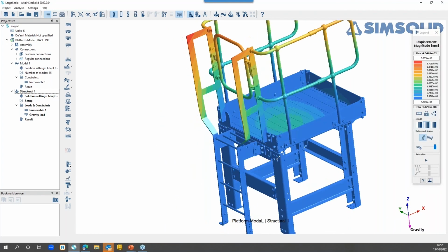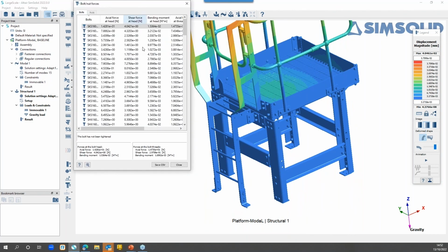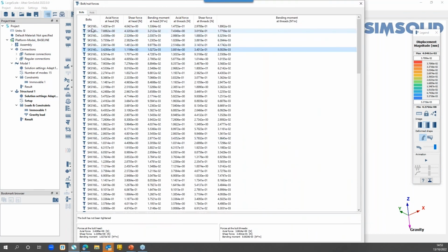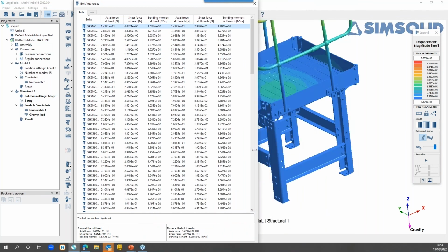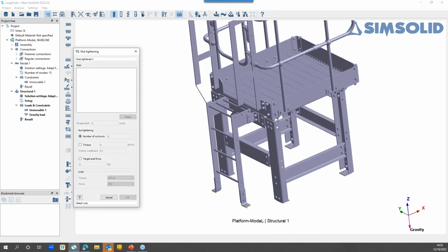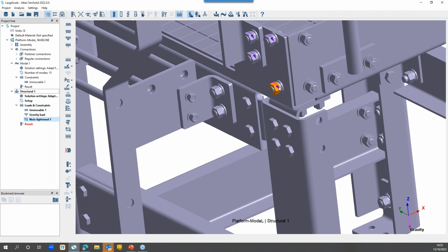There is my model. Everything looks okay, but the one I want to show you here is this. This is a whole table of every single bolt in there, which I can look at. And the one thing I didn't show you here very quickly is you can actually put, just like Nastran, you can put bolt preloads. There you go. Look, pick that nut. 1, 2, 3, 4. Pitch is 0.1. Torque is 20,000. Friction there, and there you see, so easy. And you can run it again. But because of time, we're going to move on to my PowerPoint slide.